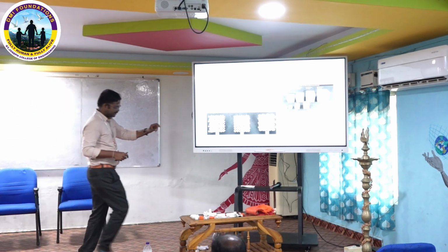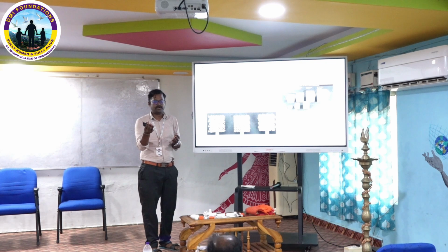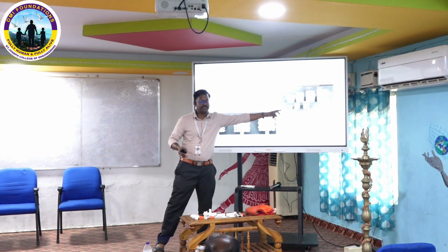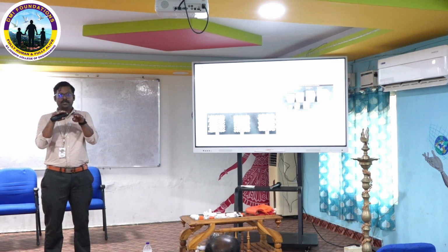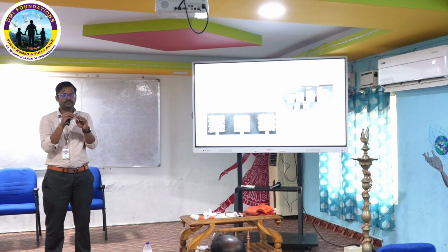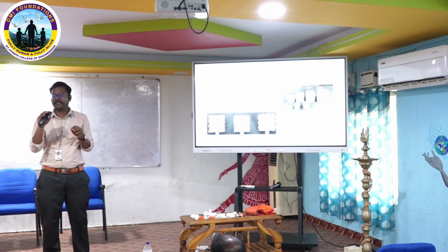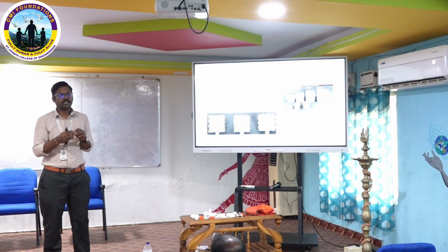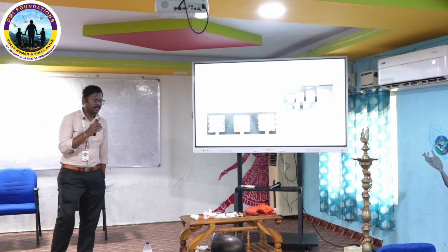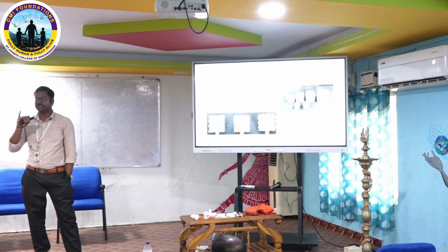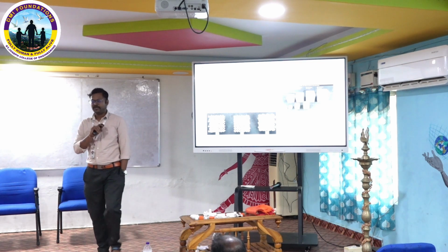Relative density is nothing but the density of the lattice structure compared to the solid structure. Say this is my lattice unit cell. I take two kinds of components: one is this kind of unit cell, the other is a full solid unit cell. By comparing the densities of both components, I get a small value, and that is the relative density. The equation is the density of the lattice structure to the density of a solid structure of the same dimension. First of all, I have to fix my relative density. Based on that, my cross section and length are fixed.